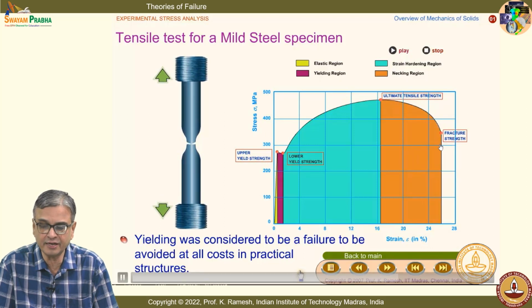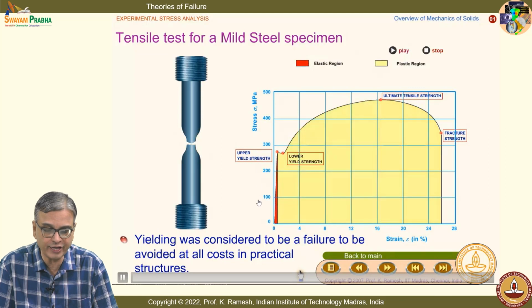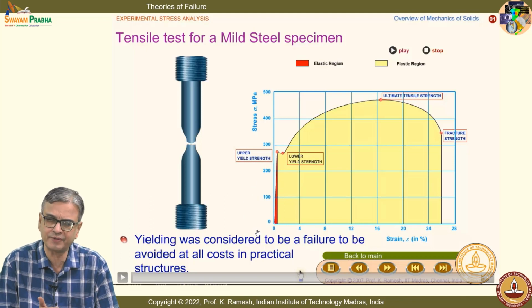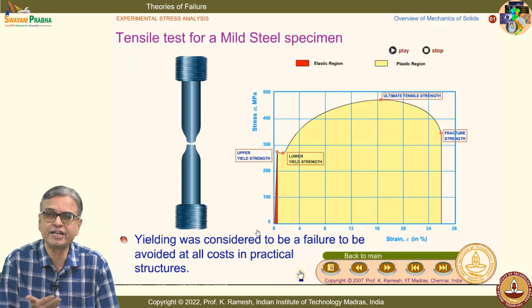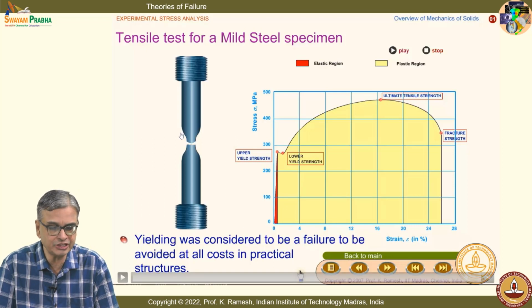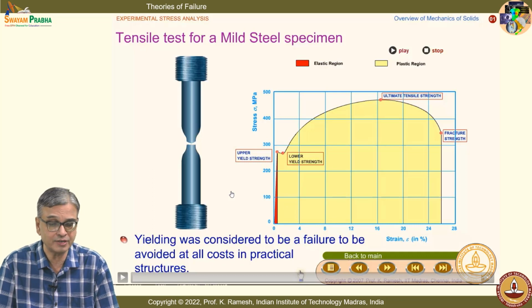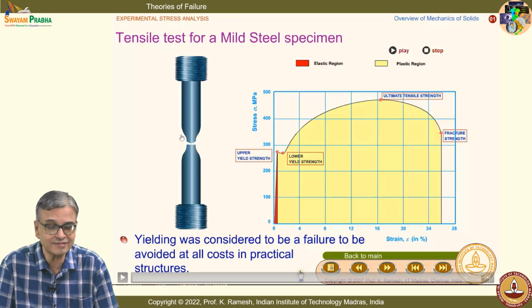And you know, in material modeling, we never attempt to model the complete stress strain curve, because many of our applications are confined to the linear region, only the elastic region, which is very small. We have seen the maximum strain that you allow to find out yield, when yield is not very clear, is 0.2%. So, you have visible change in cross sectional area, and related to this we have also looked at what is a true stress and true strain graph, because near necking you find that there is a drastic reduction in the cross section.